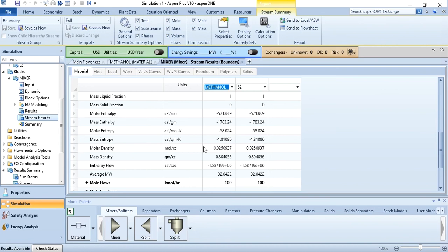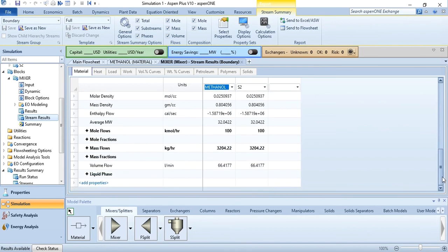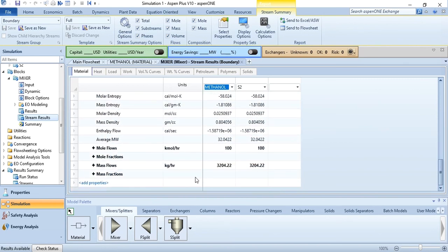And if you remember, we had talked about the density. So this density is basically dependent on the properties which you give on the specification. So you can also take these values from here as well. And same is the case for molecular weight, which we have taken, and it is independent of the properties given. Now, if you see, this liquid phase is present, there is no vapor phase present because it's a liquid entity. When you will solve air, then vapor phase will be present over here. So go to liquid phase and you see all these values are present over here.